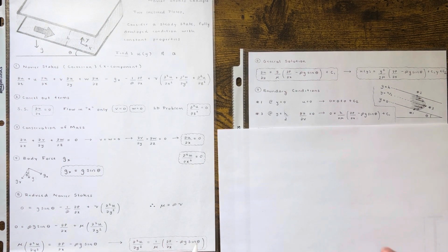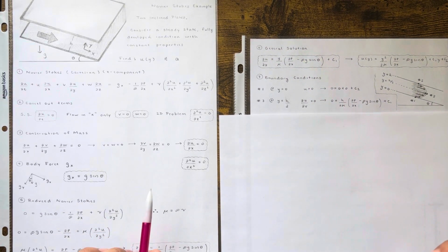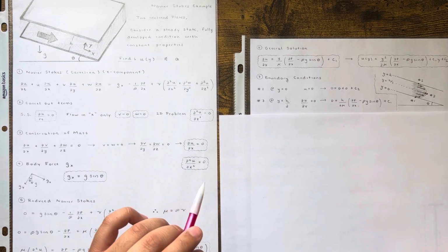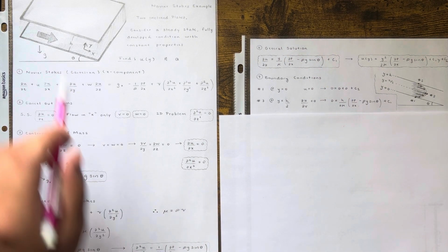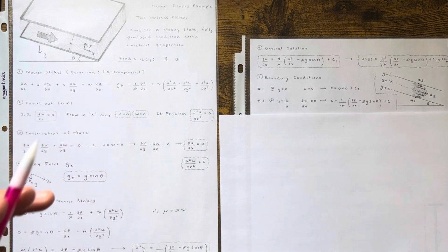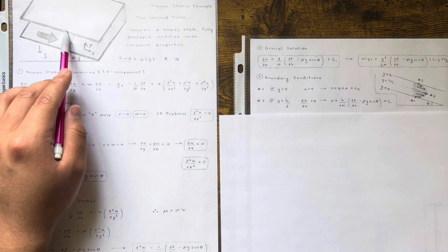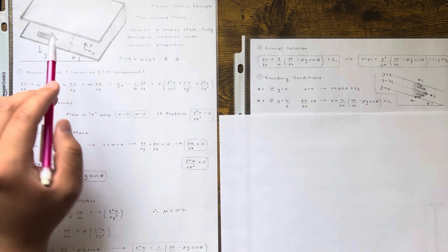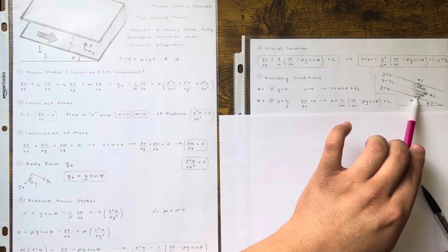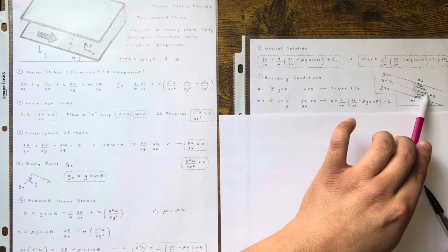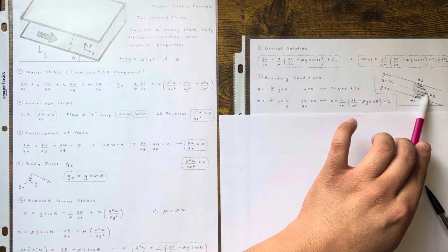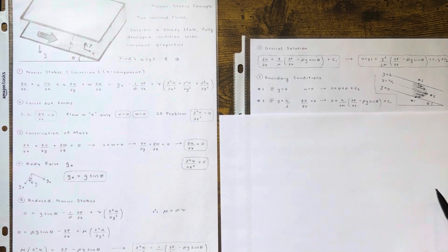I'm right here. In this case, you got to think a little intuitively. This is where the engineering mind comes in. You got to kind of predict how the flow is going to happen, okay? The 2 plates are fixed. We know because of the no slip condition that velocity at this plate is 0 and this one's 0. So I think the flow is going to look like that. It's 0 at the top and bottom and very high in the center. That's what I think it's going to look like.